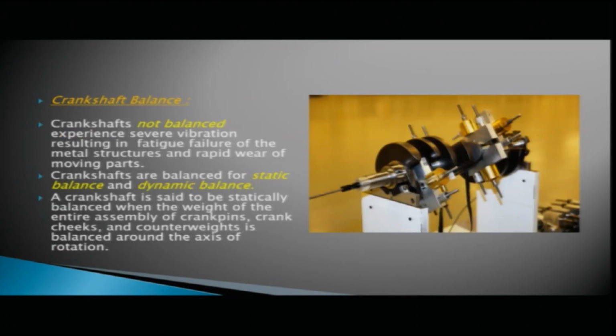Crankshaft balancing. Crankshafts which are not balanced experience severe vibration, resulting in fatigue failure of the metal structures and rapid wear of the moving parts. Crankshafts are supposed to be balanced statically and dynamically.